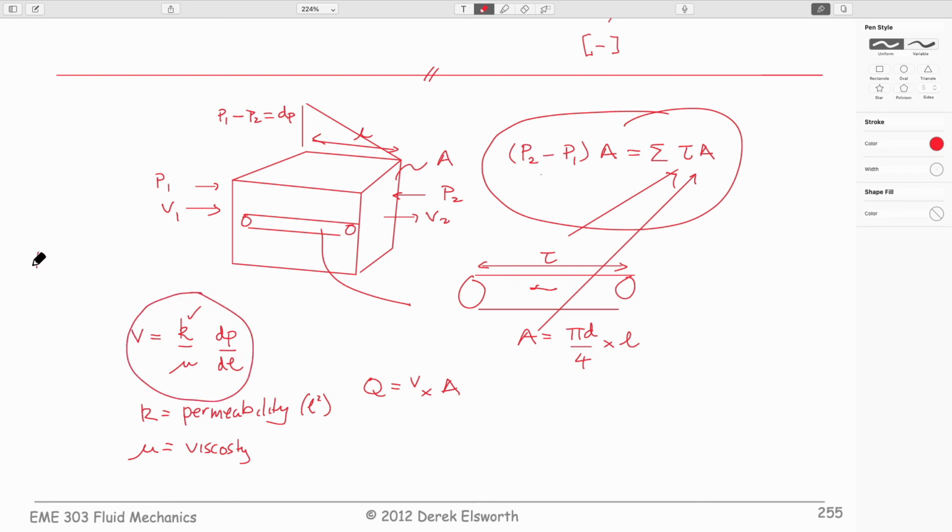This is, we already said, the Darcy-Weisbach formula, after Henri Darcy, from the town of Dijon, who was manager of the fountains. You don't need to know the story now. But it basically says that the velocity of flow is proportional to the pressure gradient, the pressure drop between upstream and downstream, multiplied by a coefficient which represents the behavior of the material it's flowing through.